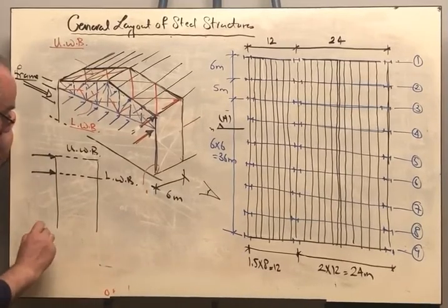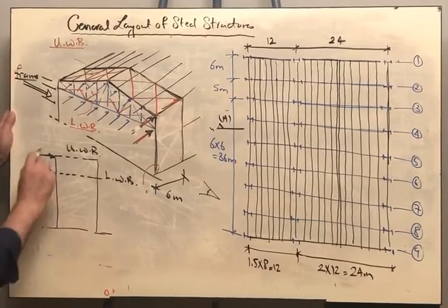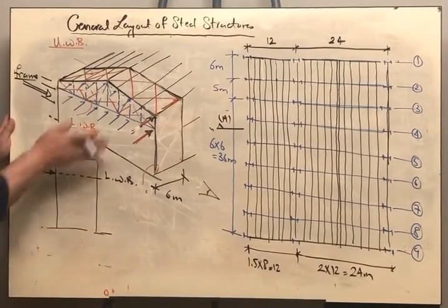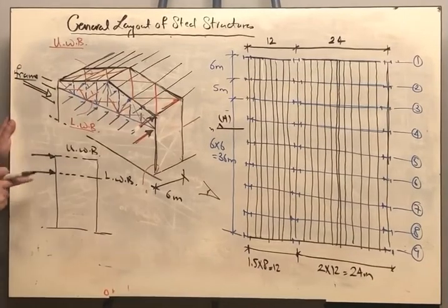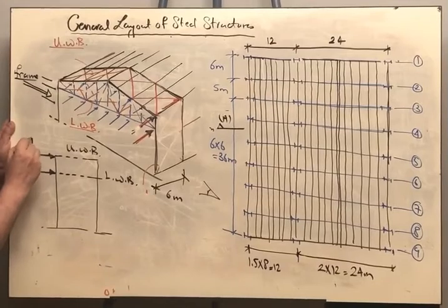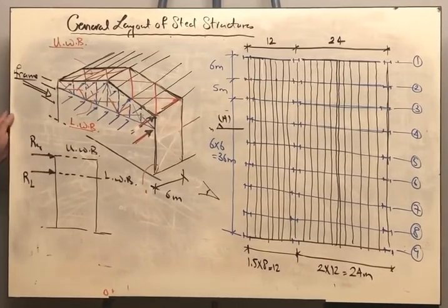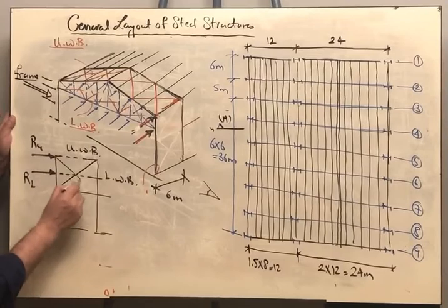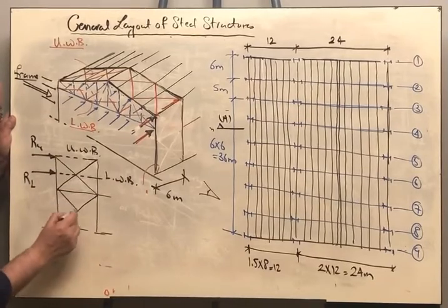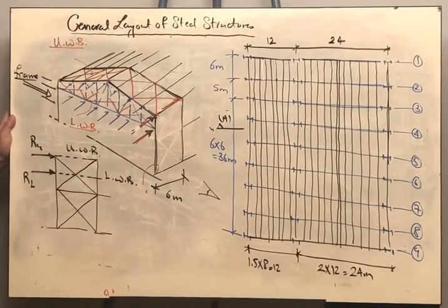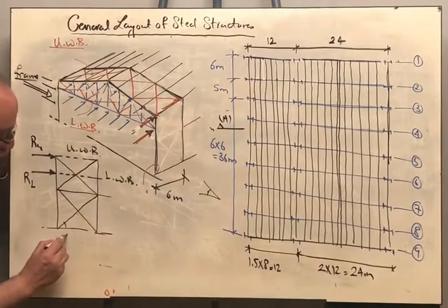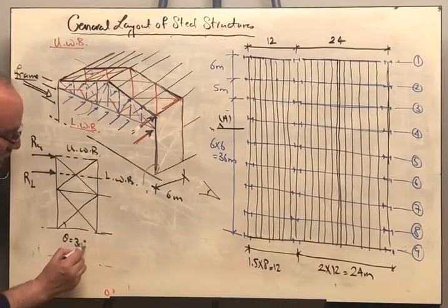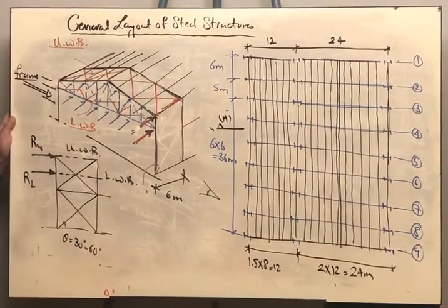Very good. Now I want to construct a truss in the vertical direction as before, in order to support the reaction caused by the upper wind bracing and the reaction caused by the lower wind bracing. One student will select this configuration as such, and he or she will tell me, I selected this configuration so that the angle, as he told us, is ranging from 30 to 60 degrees.